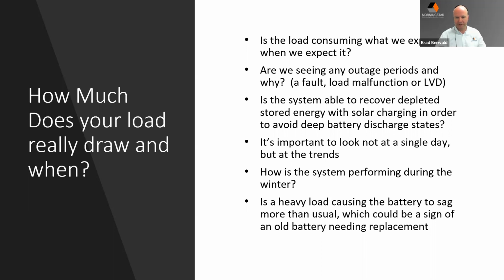And it's also important not to look at a single day, but look at different points in time. There are some load cycles that are based on days of the week. They may behave differently during the weekdays versus the weekends. They may behave differently during the same point in time during one season versus another season, because it may run great in the summer. Systems often do, but in the wintertime, you're really asking a lot of that system.